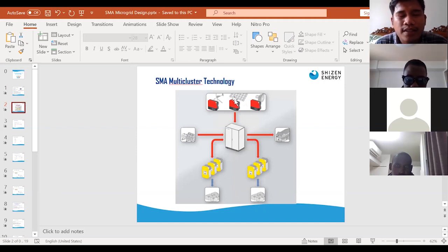But the flow is, during the night, this power from the AC will go directly first to the load, with the grid forming by the battery inverter. Later, when there is excess, because of low consumption or higher production, they will charge the battery. That's the main idea. The power goes directly to the load first, and if there is excess, it will charge the battery.